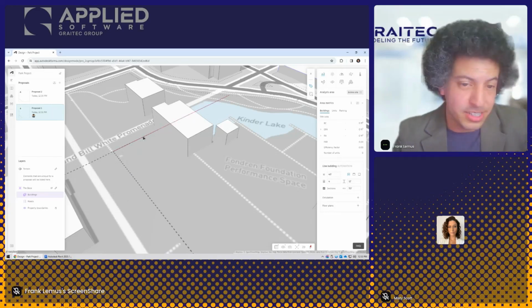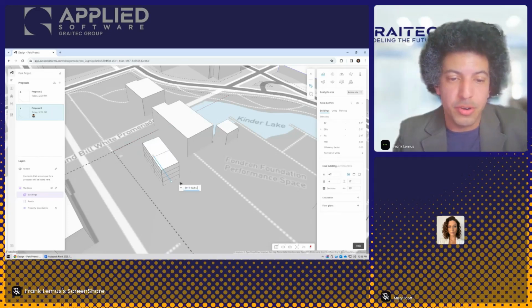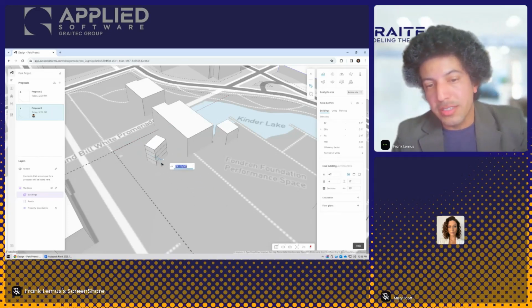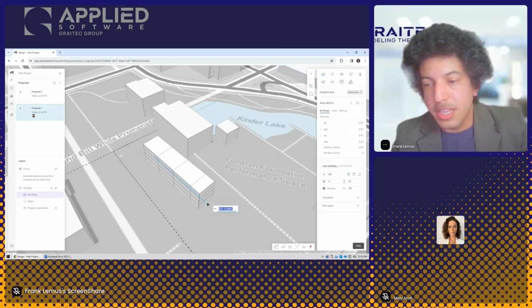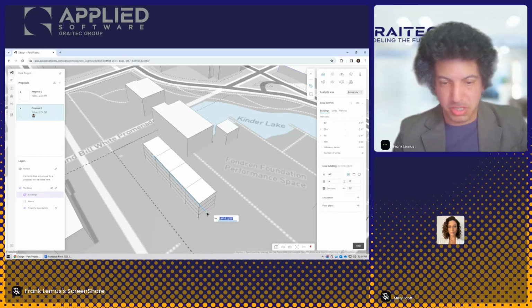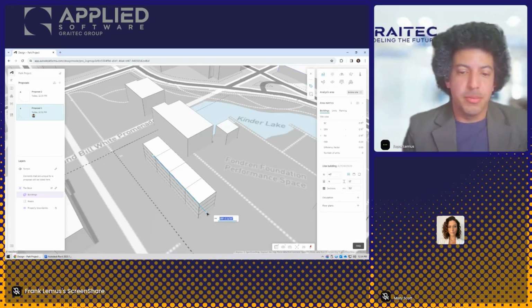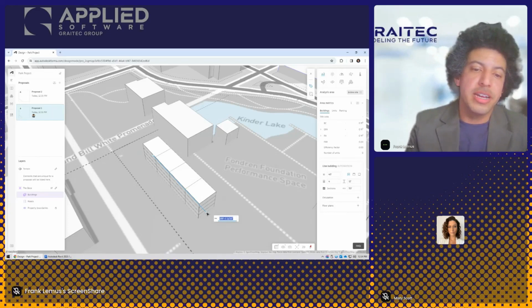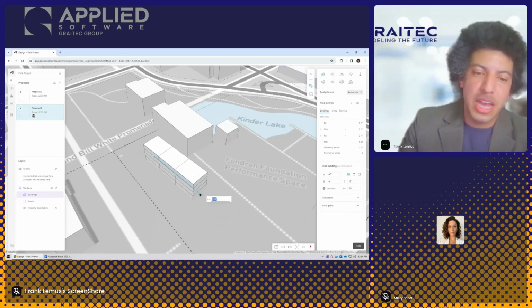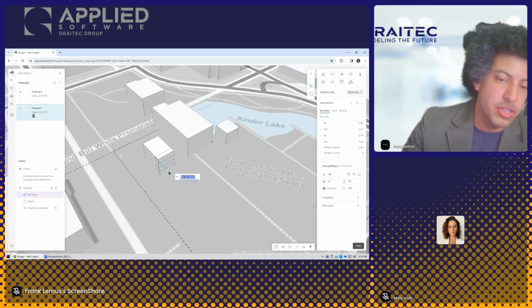Now, one thing here I can't do is interact with this as I'm creating it. I'm going to create my building starting off here, for example. You'll notice the breaks, those lines that you see going across it, those are the section breaks. In other words, it's just if we want our building to be built in sections. Really the reason we would do this is because after we create our line item, we may want to have modular control just of this first section, the floors on that first section.